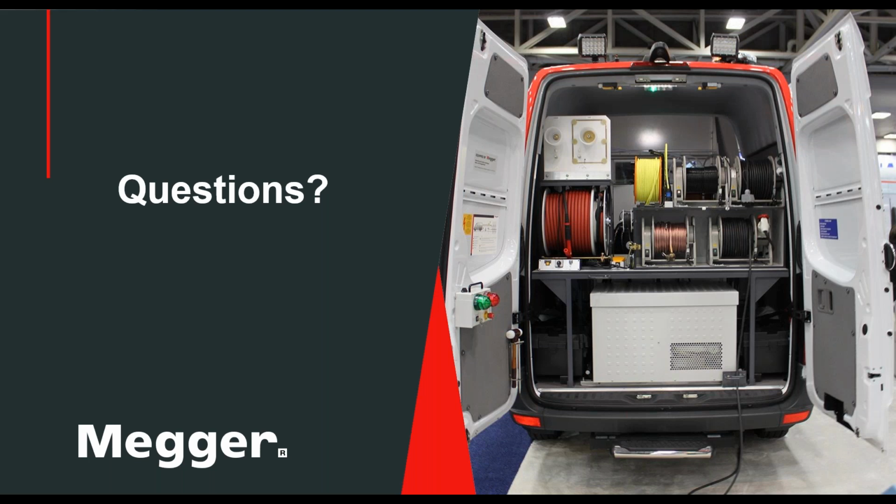So typically the radar is probably today, aside from the thumper that provides the high voltage, the most important tool in fault locating of medium voltage power cables. And it's a very, very proven tool to do so.